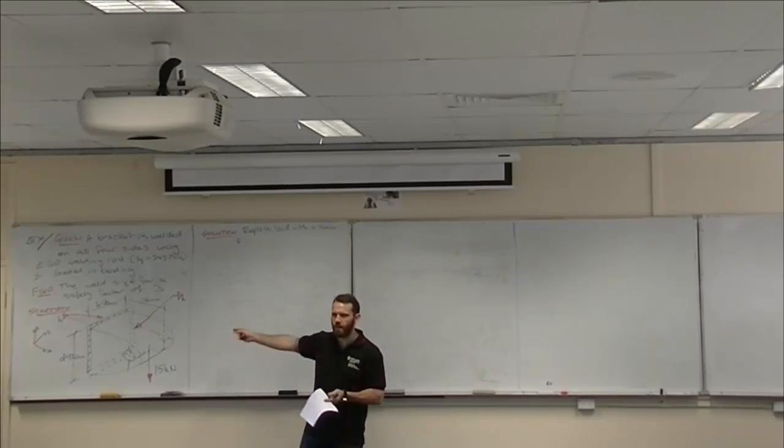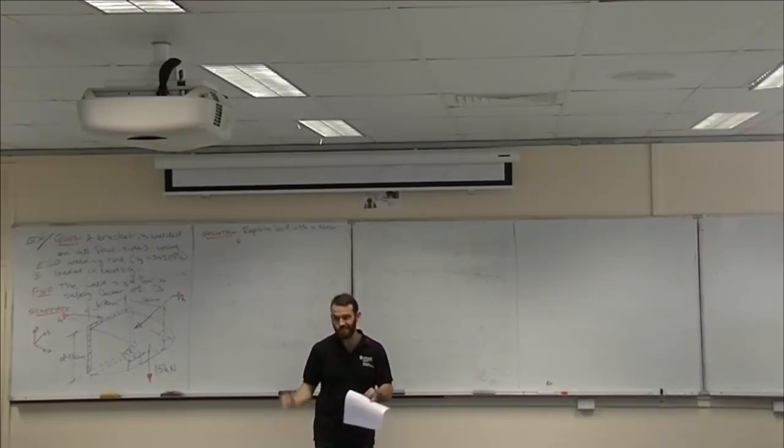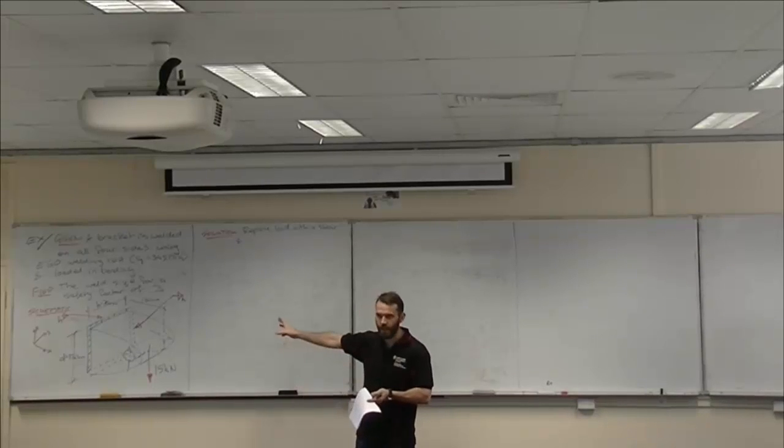In any one of these type of questions that I'm marking, even quiz questions, if you're not doing the initial layout all the way in a quiz or exam, you still need to put those assumptions. I'm being lazy here because I'm showing you how to do it. But about 3 assumptions is the bare minimum for you to get full marks for the assumptions, right? So material being homogeneous and elastic, weight being negligible, and one other is generally, if it's a shaft, then you talk about transverse shear potentially or whatever. If you've made any other assumptions, please write them down.